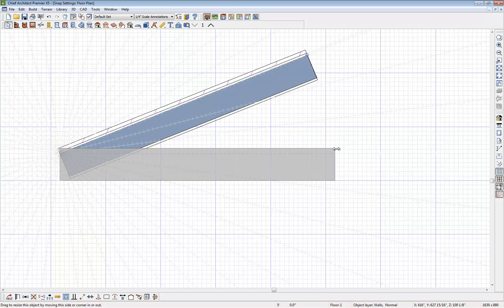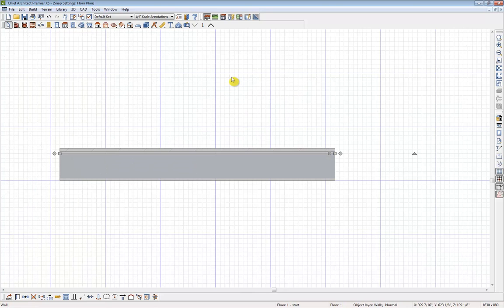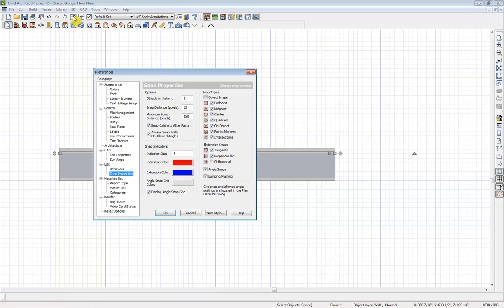So we'll have the reference for our 7.5 degree increment. Alright, I'm going to get back into our preferences and let's uncheck our display angle snap grid and move on to our object snaps. So for our different objects, they will snap according to the endpoint. So we'll have different visual references. We'll have the red box for the endpoint, a triangle for the midpoint, and so forth.